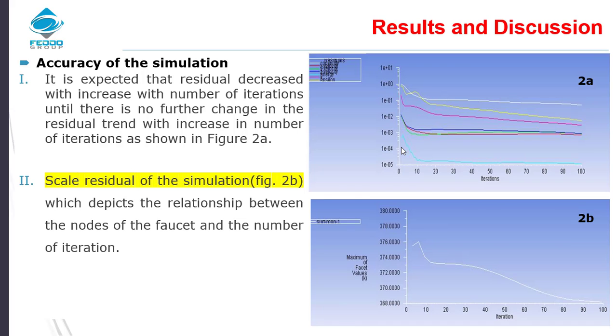When you talk about the residual and the convergence tolerance, it is recommended, according to schools of thought, research and standards, that the scaled energy residual decreases to a convergence tolerance of about 10 raised to minus 6, while the scalar species may only need to decrease to a convergence tolerance of about 10 raised to minus 5, to achieve energy and species balance respectively.